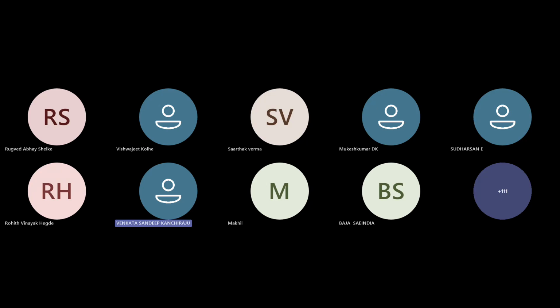As you have already tested in IPG and ended up with 500 kgs, after this workshop you know where exactly the weights have to be defined. Remove every weight we have said in those individual sections, and add the remaining weight in the vehicle generator data set. After that, you add all these individual weights and you will get your accurate vehicle.